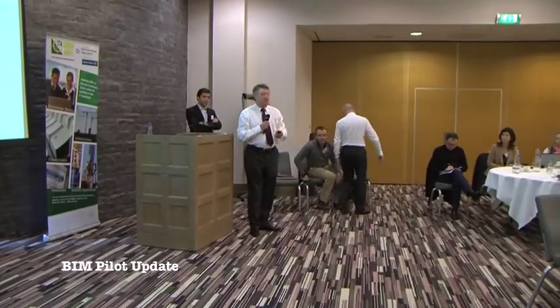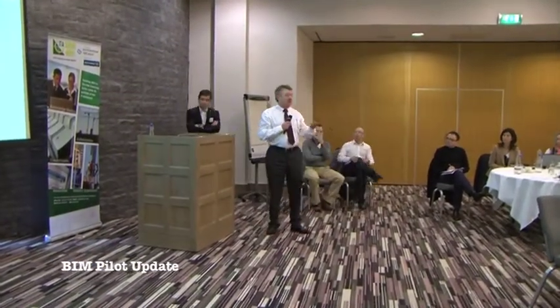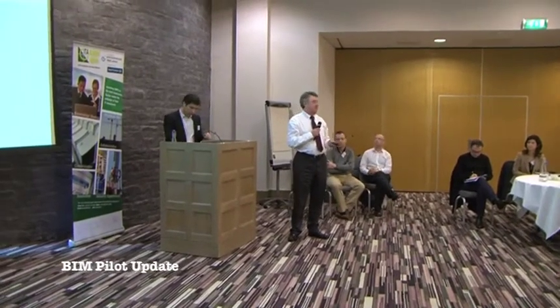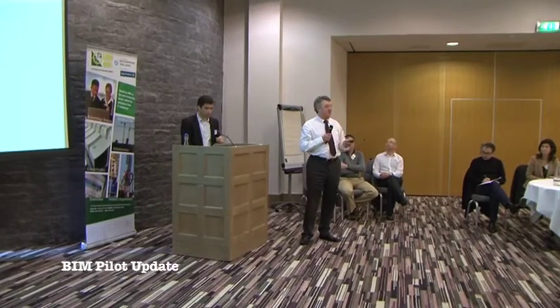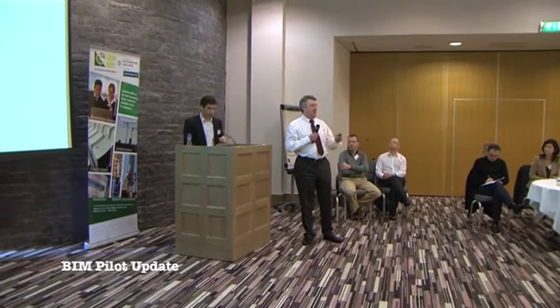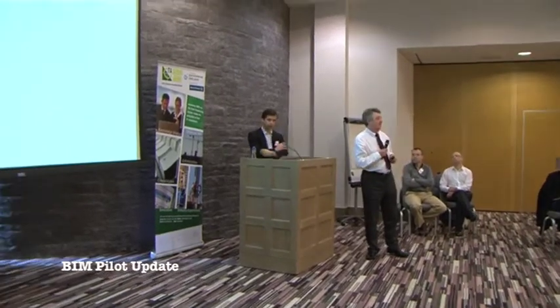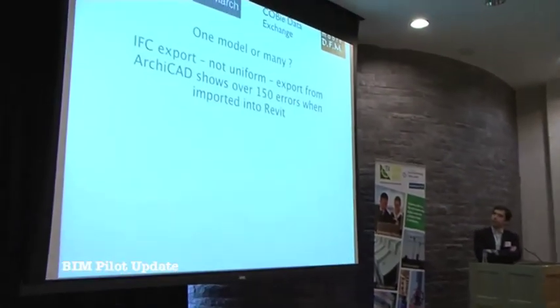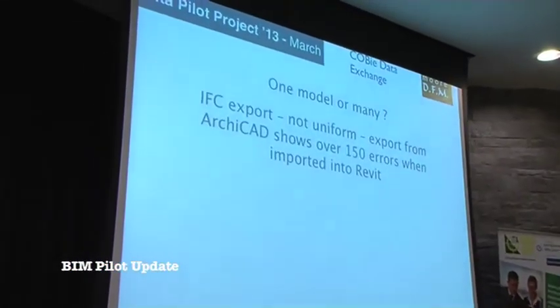Okay, we're talking about COBie data exchange. From our point of view, from facilities management and handover documentation, operating and maintenance, our deliverables generally only come in at the end of a project, but in a true environment, we should be gathering that information as we go along. And the standard format for the exchange of that information is the COBie data exchange format, Construction Operation Building information exchange format.